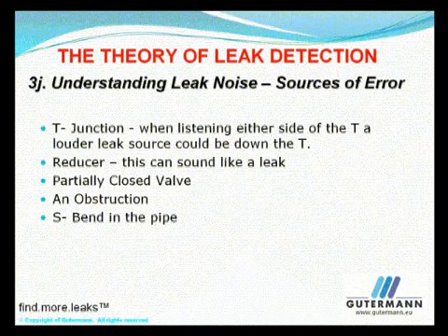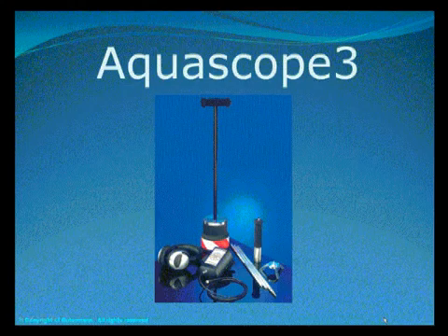When the pipe depth changes or the concrete slab level changes, it is very easy to think you've found the leak because there is a big change in noise level. This is a difficult situation you may not be aware of unless you've used a locator to plot the pipe positions and the depths. You may need to drill test holes or push a mighty probe onto the pipe, making direct contact between the pipe and listening stick to accurately pinpoint the leak.